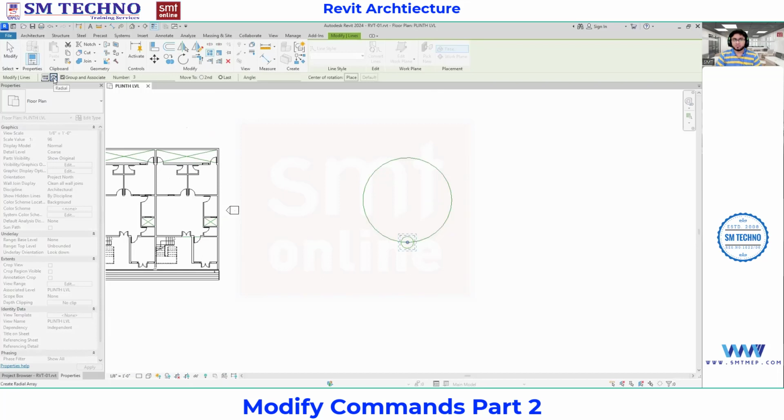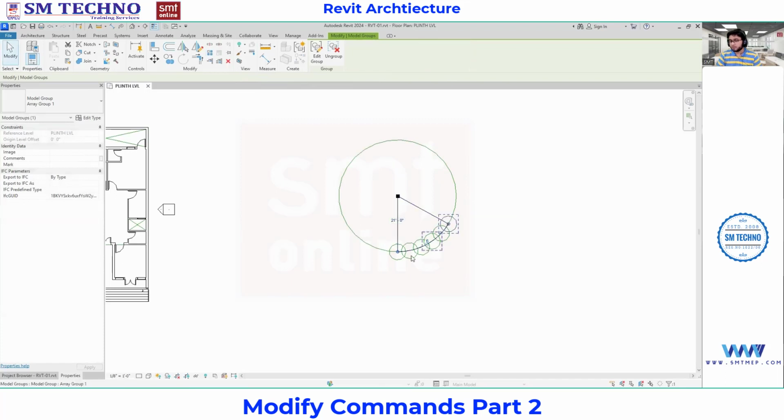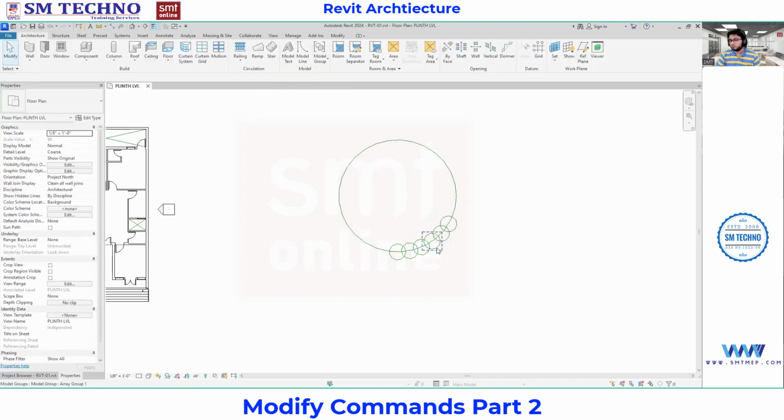Now here we have the option of radial. In the radial, you can specify the group and associate, which should always be enabled. Now specify the center of rotation, the point from which you want to rotate. Right now it has selected this point, but I want to rotate this object from this reference angle. How much is the angle value you want to rotate? Like 30 or 60 degrees. And how many items do you want? Like 12 items or 6 items. 6 items I use. So between this angle and this angle, 6 objects are placed over here, between the 60 degrees of angle.